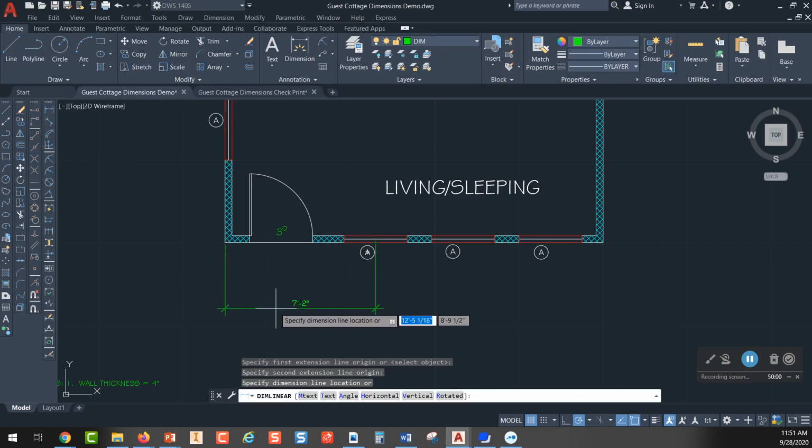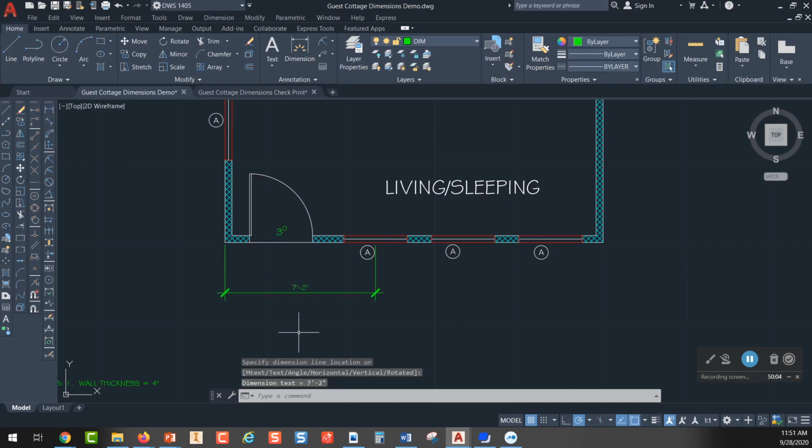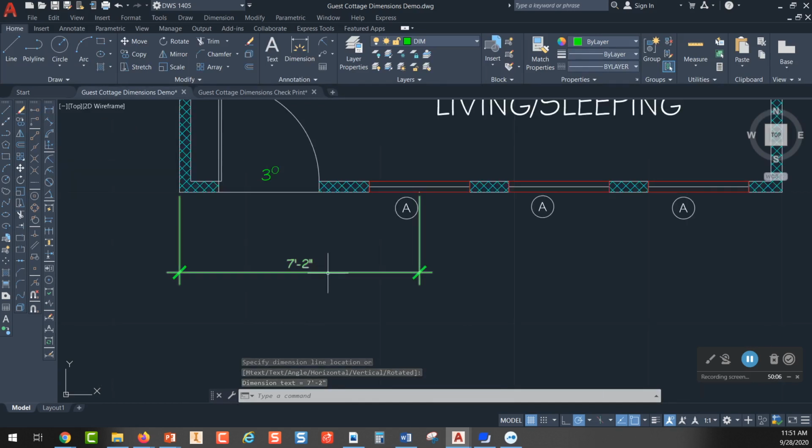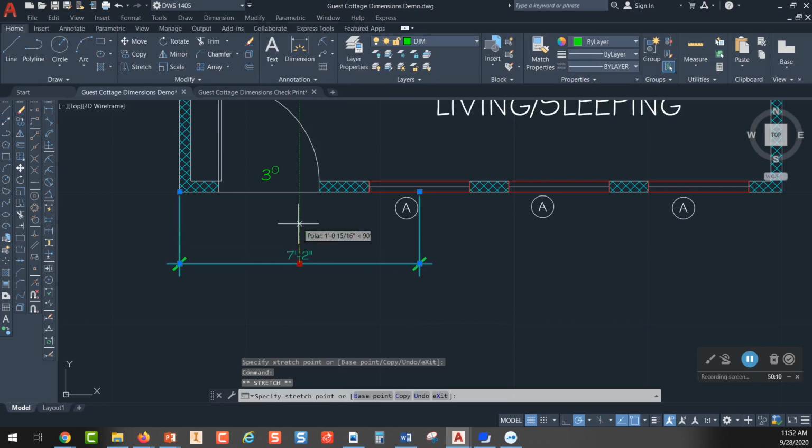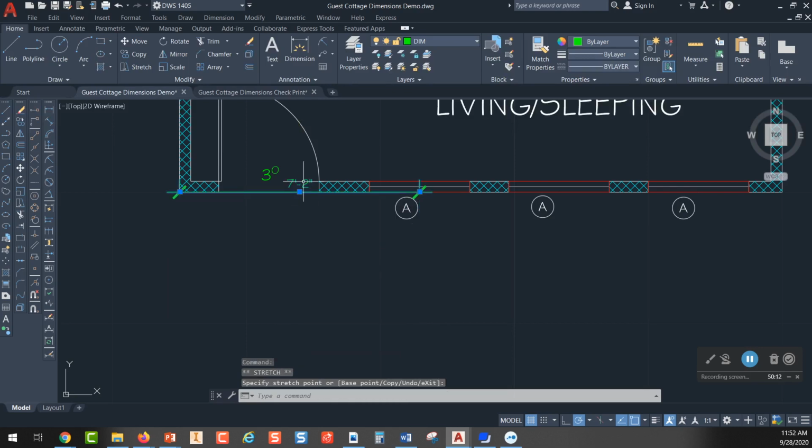Now, how far do I move out? This is that thing I was telling you about, where you want to move out 27 inches. So one way to do that would be to drag everything up and set it right on your exterior line, and then pick and hold down and drag it and type 27 and enter, like that.